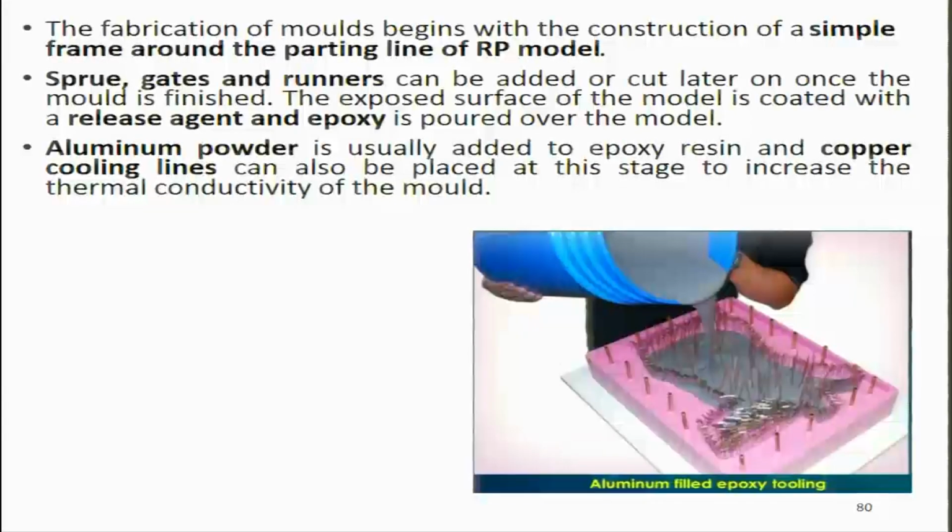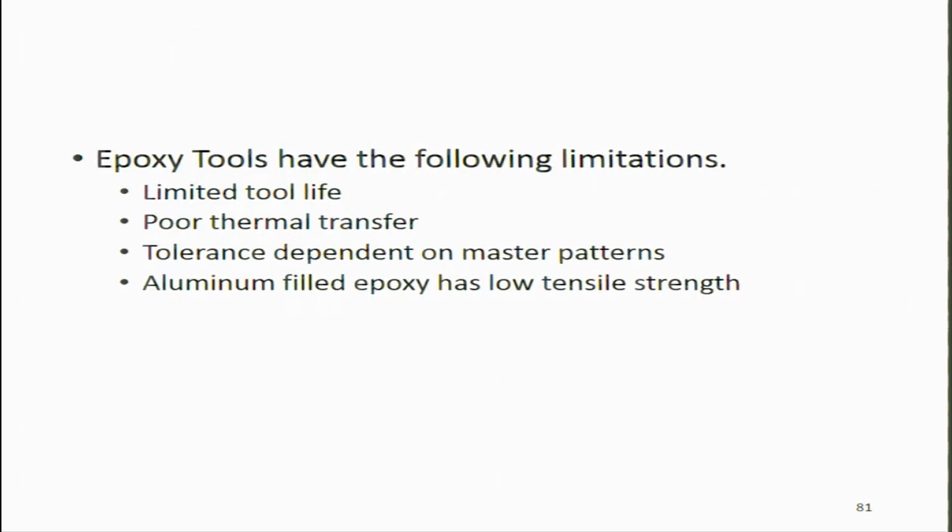The advantage that these epoxy tools have is, number one, that they are made of a slightly harder material, so they last longer in comparison to what you saw in the silicone mold or the rubber mold. However, they have limitations. You have a limited tool life, again poor thermal transfer, and sometimes you have to intentionally make cooling lines happen because epoxy itself is a thermally insulating material. You also have a tolerance dependency on the master pattern.